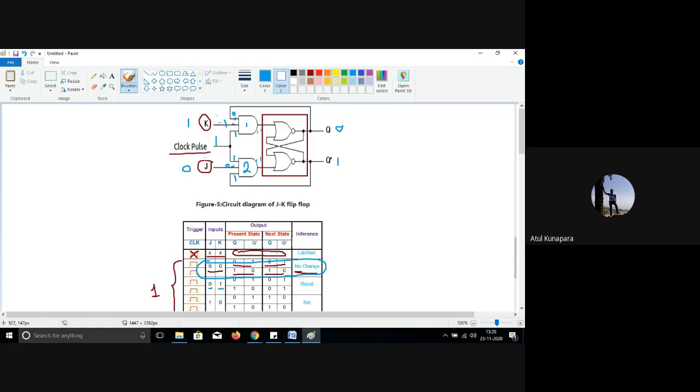Here either there is a mistake in writing J and K or something, because this is also giving the 0, 0 condition, because 1, 0 is coming here also and 1, 0 is coming here. Either that J and K should be reversed. Maybe J, K inputs are reversed. Just a minute, let us check this diagram. I think there is a cross connection coming at the output side.